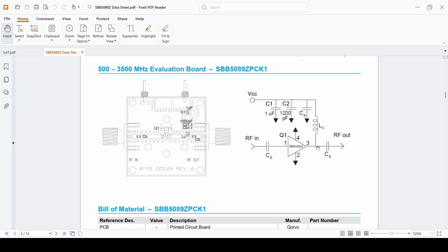And what is high impedance at high frequencies? It's an inductor. It's very low impedance at low frequencies, so it can easily pass high DC currents. But at high frequency, you can assume it to be a high impedance or a floating component, right? That's why we use an inductor when we want to provide the supply voltage here, because not only does it not load the output at high frequencies, but it also acts as a filter, filtering whatever high frequency noise our supply has from the output of our amplifier.